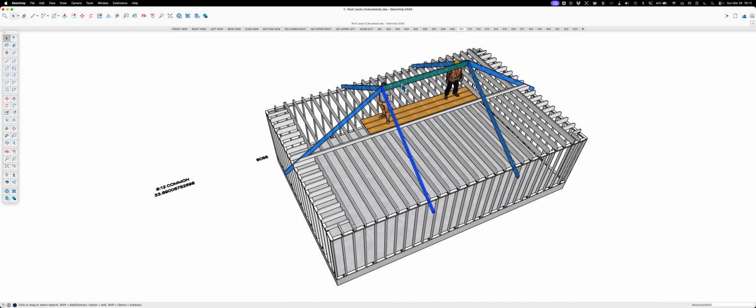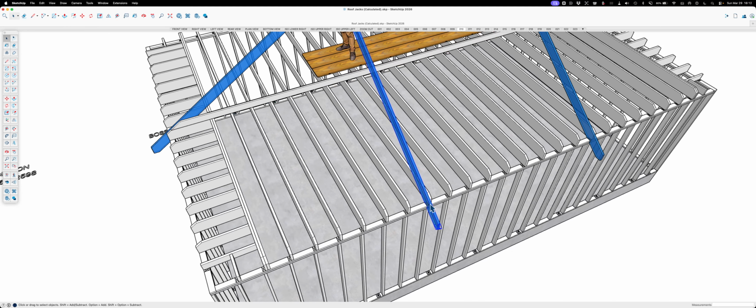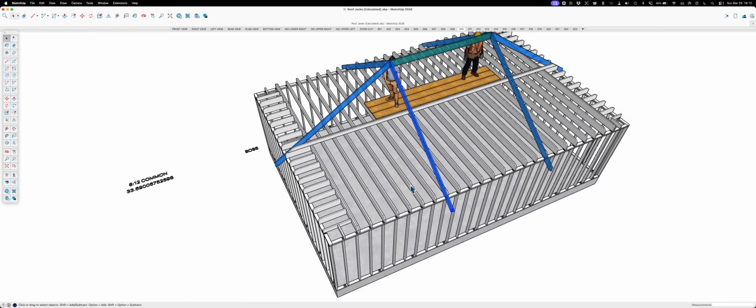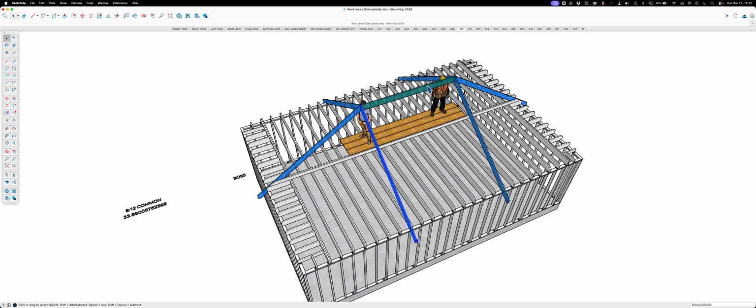Once you've laid out this building, you can actually measure from the layout to over layout, and you'll know exactly how long your ridge is. That comes in handy sometimes when you're doing a more complicated roof. You can send up a ridge and maybe only make it a foot longer, just so that maybe they need to nail something to it, like a floating hip or something. But anyways, this is the full skeleton, and now it won't go anywhere because it's nailed on all sides, so it'll feel pretty solid.